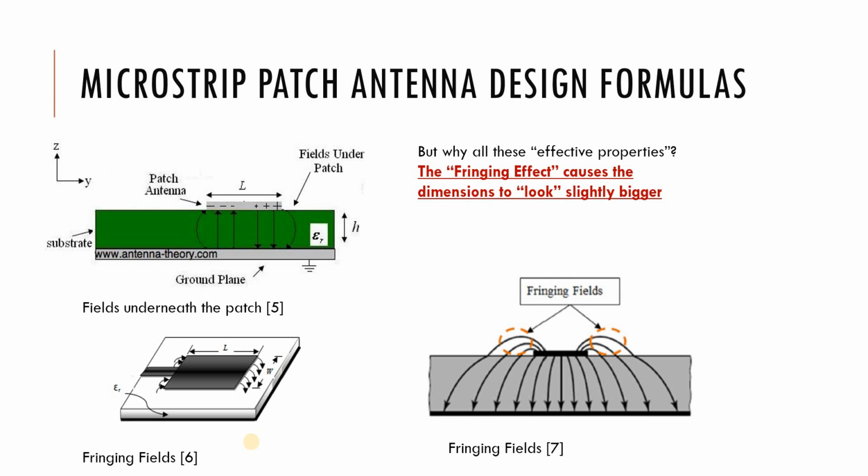As I said, it's the fringing fields that are responsible for the radiation. Fringing fields are near the surface of the patch antenna, both in the y direction and minus y direction, and since the fringing electric field takes place on the edge of the microstrip antenna, it adds up in phase and produces the radiation of the microstrip antenna.